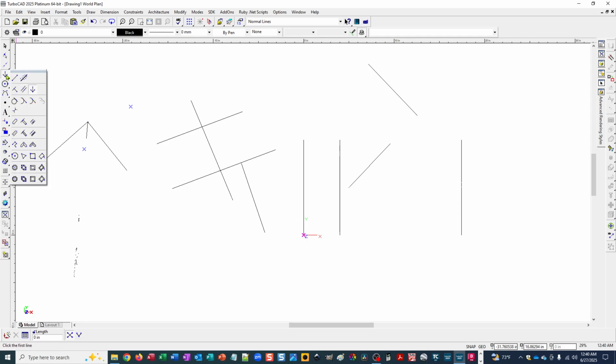And just to illustrate again that they don't always have to be a V formation, I'm going to draw 2 lines using the regular line tool in an X formation. Now I'm going to go back to this bisector, and I'm going to click my 2 lines. And now I'm going to click. Notice in this X pattern, it's showing temporary point markers to tell me where I'm referencing.